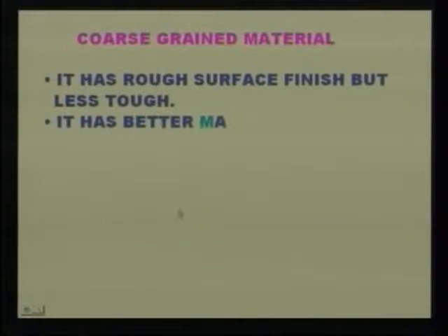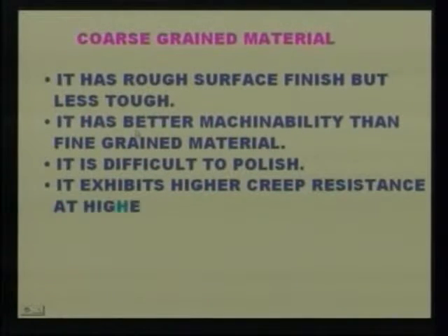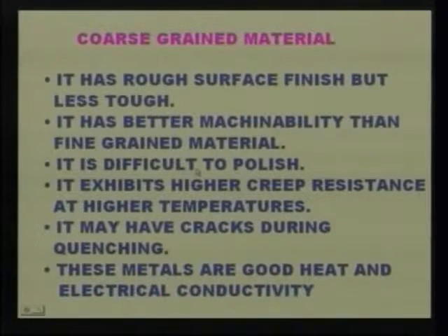Now you can see the coarse grained material. It has a rough surface finish and is less tough. It has better machinability than fine grained material. It is difficult to polish. It exhibits higher creep resistance at higher temperatures. It may develop cracks during quenching. These metals have good heat and electrical conductivity.